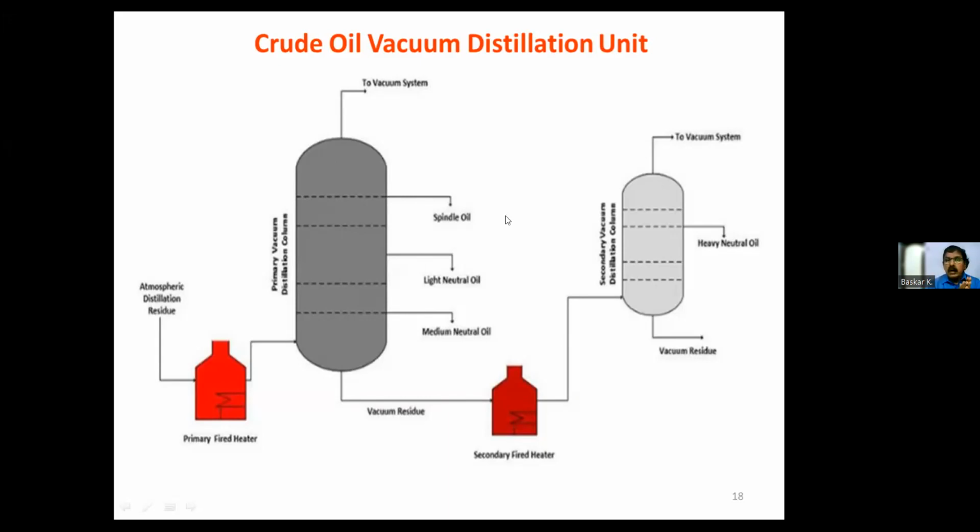In the crude atmospheric distillation unit, we are maintaining atmospheric pressure and normal temperatures. And in the vacuum distillation unit, we are maintaining vacuum at 600 mm AG to lower the boiling point of heavy ends, so that our purpose of distillation takes place. So now we have distilled all the products from the crude oil, from LPG to the vacuum residue, which is basically fuel oil. The entire product is being distilled out, right?